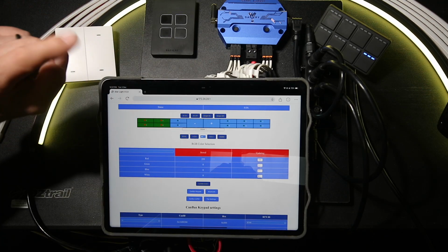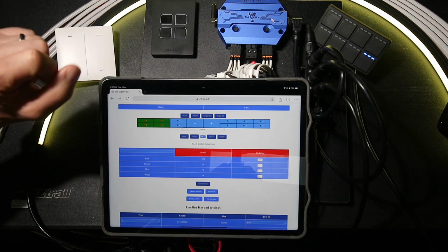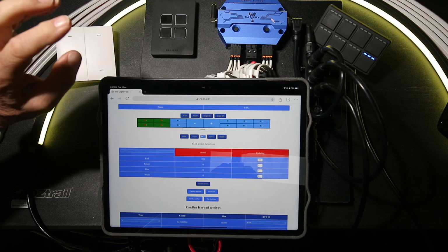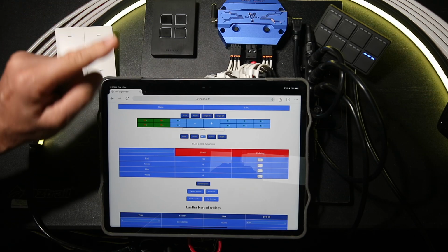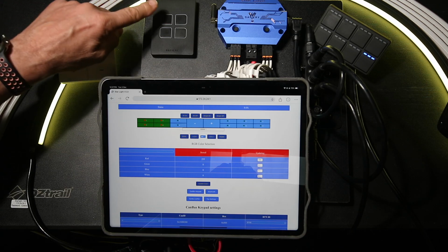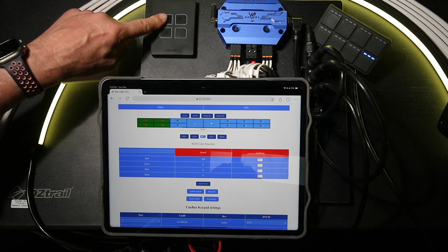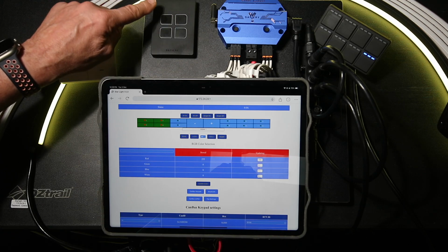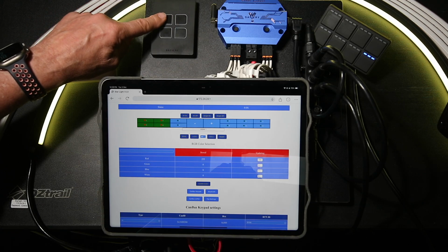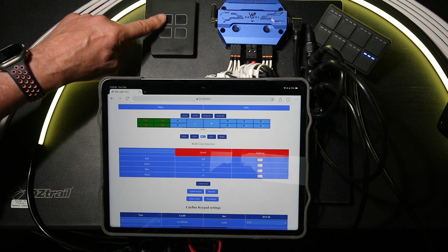You can have up to 6 buttons assigned, and they can be a mixture of the CAN wired and Bluetooth to 1 output channel. So you can have up to 6 assigned to it, and you can have 1 as a master. So if you go through and always assign this button at the top here to turn on and off all the channels, then on that controller, when it's pressed, it will clear and turn off all the channels. You can have a submaster, you can have a master, you can have any logic there that you like in how you group them together.